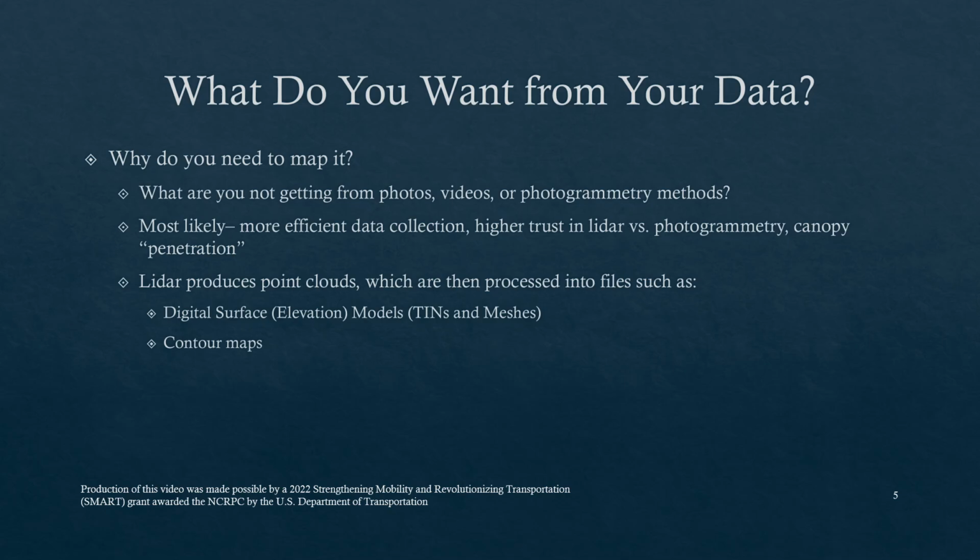So what do you want out of your data when considering using LiDAR? You need to think about what you're not getting from photos, videos, or photogrammetry methods. It's important to try to use the simplest technology or means of data collection first before choosing something more complicated like LiDAR. It's a good rule of thumb if you're getting to the point where you need mapping: photogrammetry can really do anything that LiDAR can do, except for what I'll talk about a little bit later. So if you can use photogrammetry, try that first before making the jump to LiDAR.